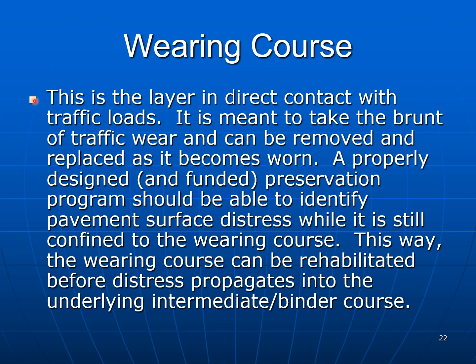A properly designed and funded preservation program should be able to identify pavement surface distress while it is still confined to the wearing course. This way, the wearing course can be rehabilitated before distress propagates into the underlying intermediate or binder course.